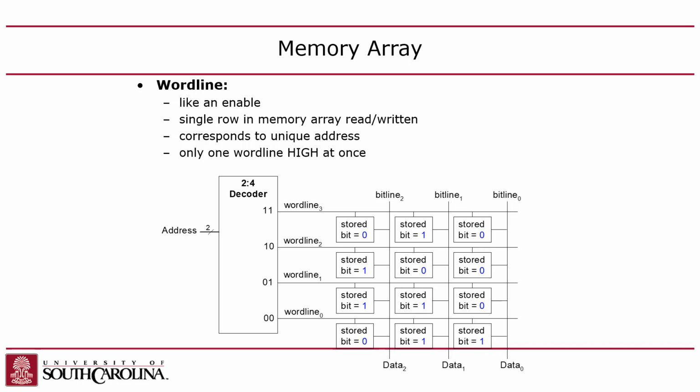And when the word line is activated, it'll connect the bit line to that word, to that row, right? And that allows you to read out. Now, when you do that, you would have to drive the input bit line to high impedance because you wouldn't want to write to it. But if you do want to write to it, then you can set the bit lines and just write into that word. You guys with me?